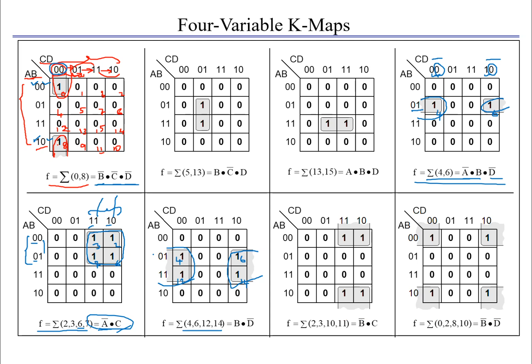As far as this case is concerned, see here, these A, B combinations are considered and C and D, these 2 are considered. And we need to find what the common variables are here. A is varying from 0 and 1. It is A bar A, hence it turns to 1. And B is common and it is equal to 1, hence it is equal to B. We are writing it as B here in the simplified expression.